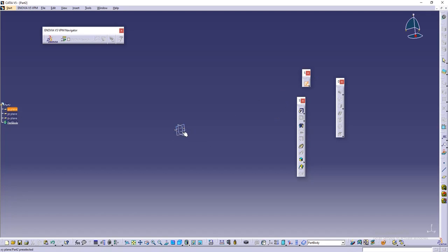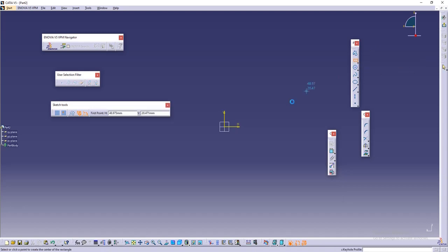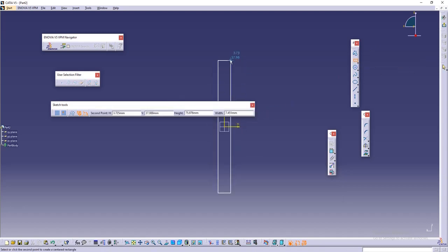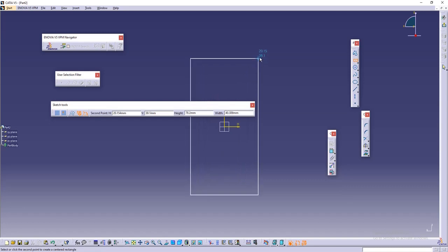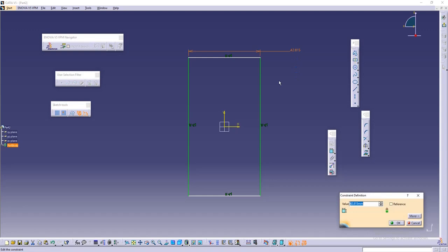So first, select the plane, whatever plane you want to create. It will guide you to the plane. Then I will select the center rectangle, and then I will go with the dimensions of the mobile. Click here. It is already H and V, horizontal and vertical lines are aligned. What is the next thing? Next thing will be the dimensions. How much will be the dimension? It is showing 42. Maybe I will take 60,